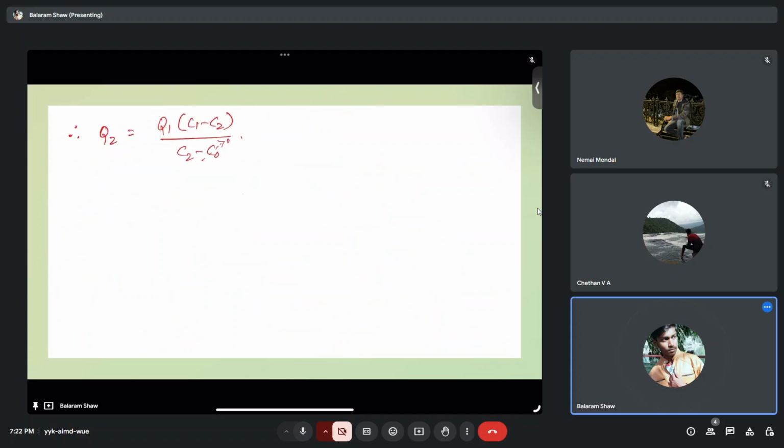Okay, as I mentioned, there is the electromagnetic method, which follows Faraday's law, and based on that principle we can get the discharge again. So what is the main advantage of the electromagnetic method? It is non-intrusive. We can adapt it at any place because we are not doing anything in the water stream, not doing anything mechanical, right? We can also do continuous monitoring. But the limitation of the electromagnetic method is that it is only applicable for streams of around a maximum width of 30 meters.